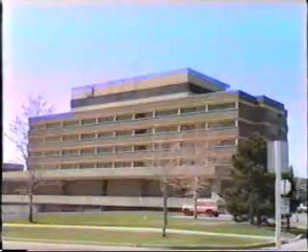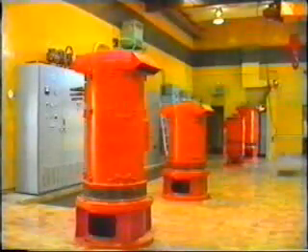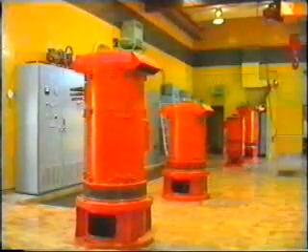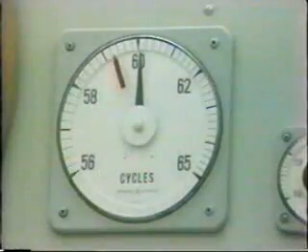Essential loads, such as hospitals, pumping stations, etc., are not normally included in load shedding schemes. Although it is highly undesirable to disconnect any customers, this is the only manner by which recovery can be achieved. Once the frequencies are normalized, then the power systems can be reconnected and interchange can begin once again.